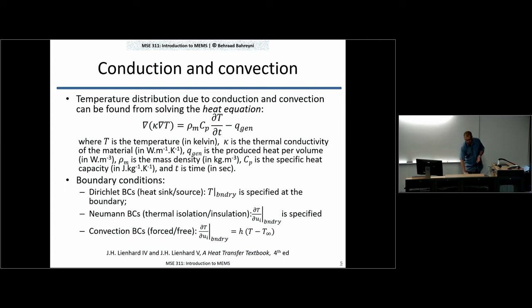So in that case, you have some constant that determines the efficiency of your convection mechanism. The T at infinity: you're removing heat from here, moving it to somewhere far, hopefully. So what is that far location temperature, and then what is the location at this point? Those are the three typical boundary conditions that you have to solve the heat equation with.